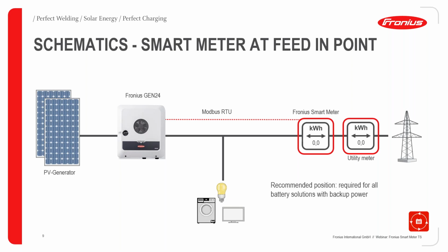And then after the utility meter, there is usually a sort of post meter protection, like a fusing in between. And after that, we usually recommend the Fronius Smart Meter to be set, because that's actually the central collection point.